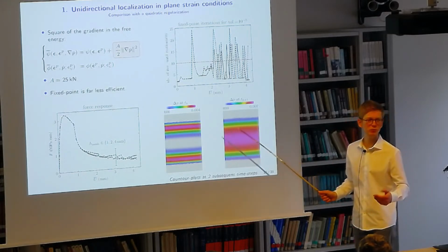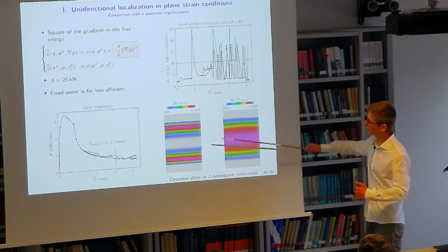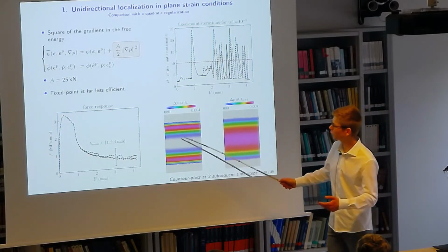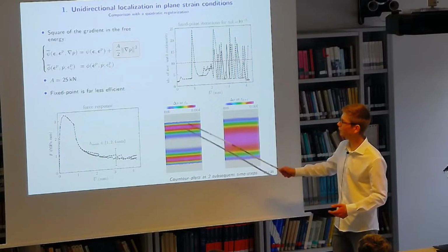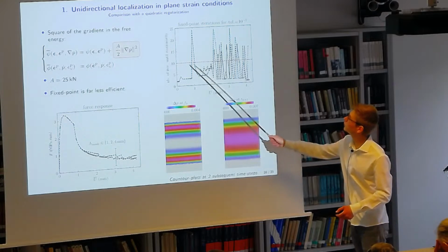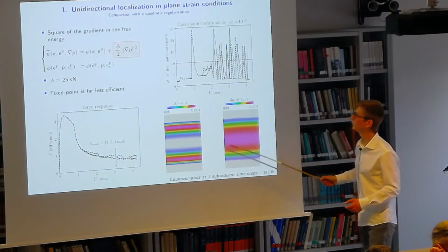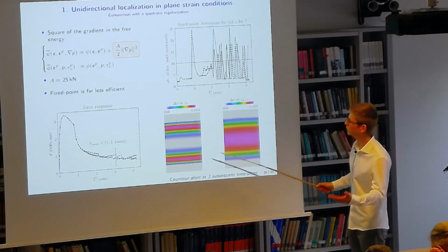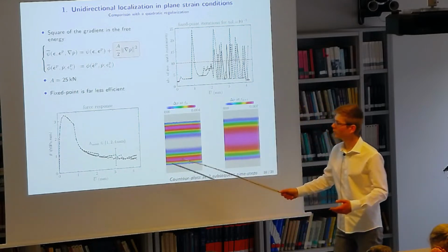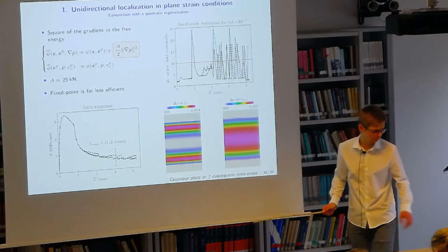It seems that we switch between two modes of localization. On the right, something which would be expected, a symmetric one around the middle of the sample. On the other hand, a kind of localization with two bands at both extremities with an elastic unloading in the middle of the sample. This is the cause of the different behavior in the number of iterations, either a large amount or a low amount, between these two kinds of localization observed at each time step. At the same time, during the evolution of the force with the displacement, we also have this erratic evolution, even when changing the mesh size used.